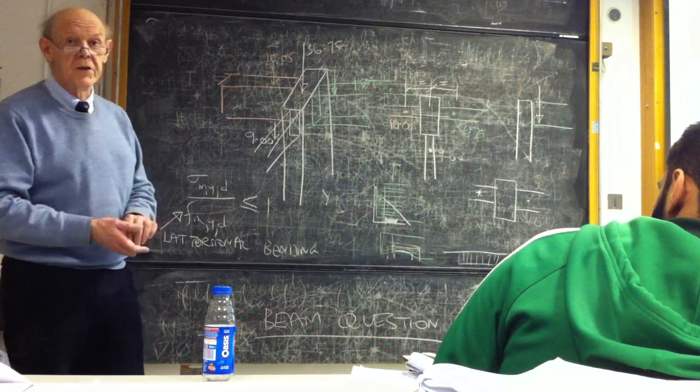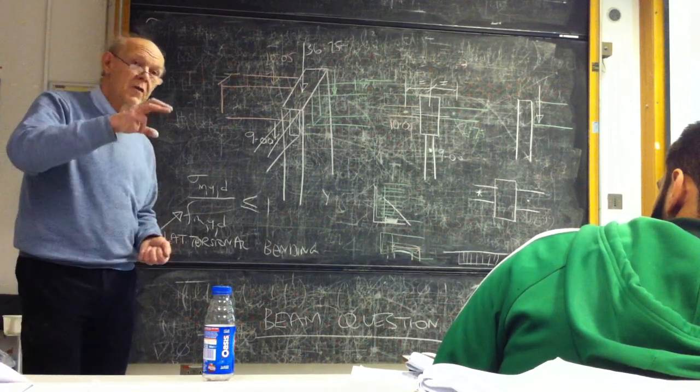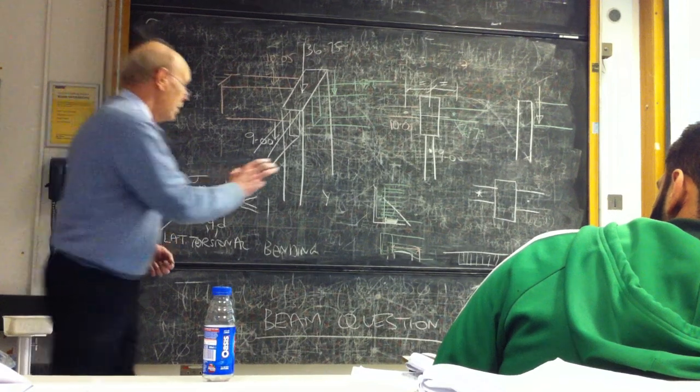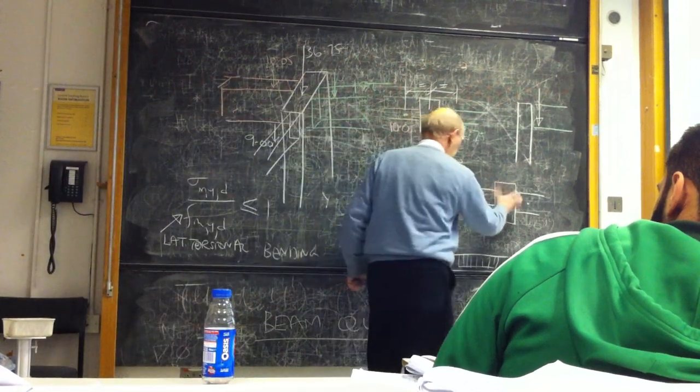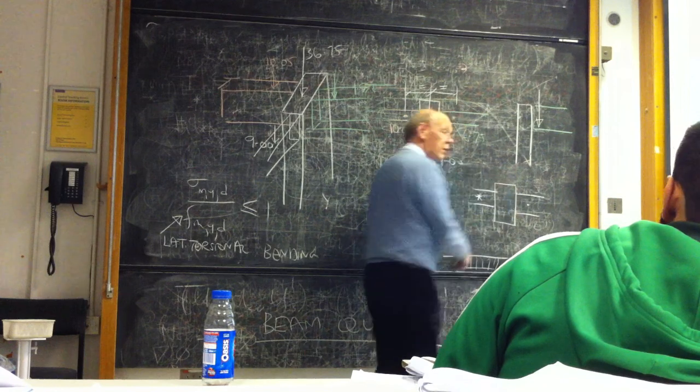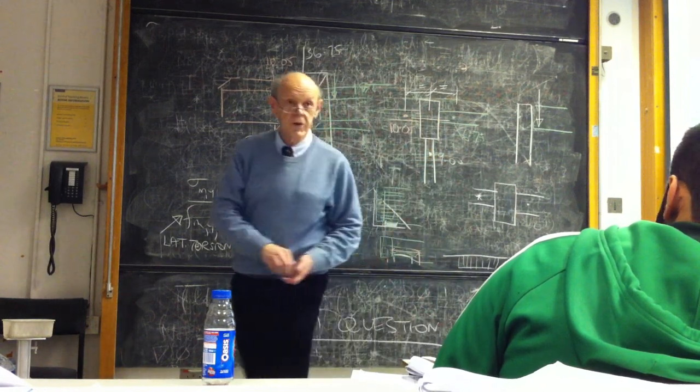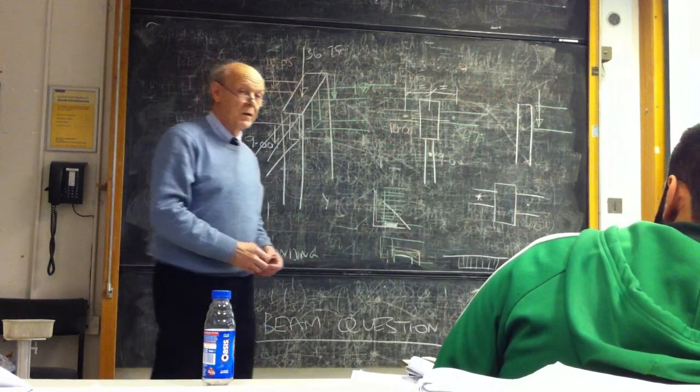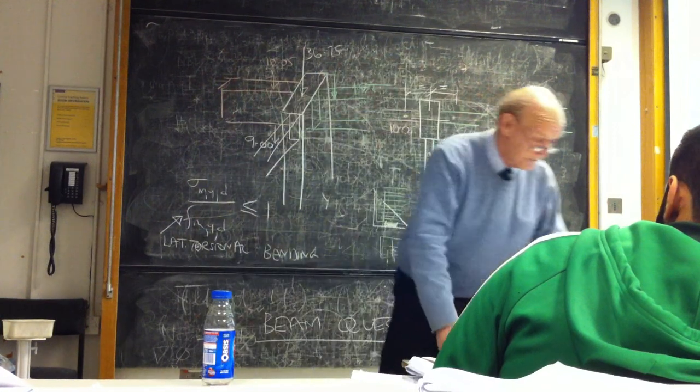But if there's a series of restraints, you've got to make sure that even though it's being bent about this axis, it might buckle about that one, if there are sufficient restraints of the z-axis. So you check about both axes, always.